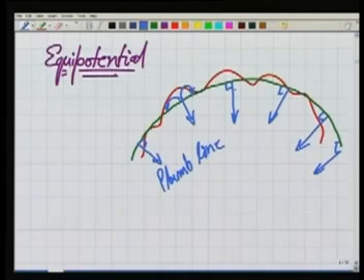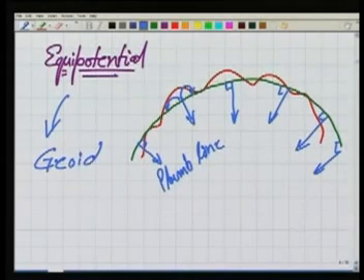So this kind of surface we can term the geoid, and we have seen this before also in our very first few lectures, when we were talking about the basics of surveying. We again discuss this surface, the geoid. Basically we should use the geoid as our reference, because it is related to gravity. This helps us because in our civil engineering projects, height means the water from a higher point should flow to the lower point. This cannot be realized by a horizontal surface. This will only be realized if we start measuring the RLs or elevations.